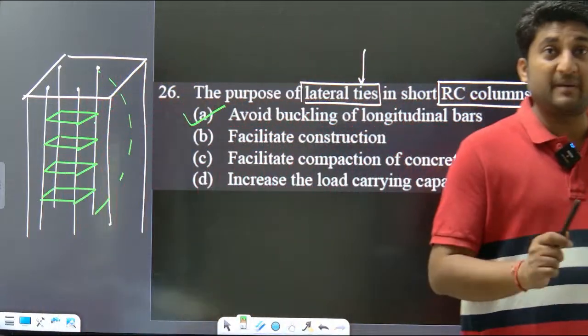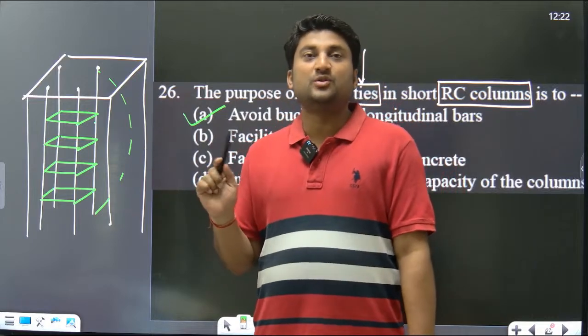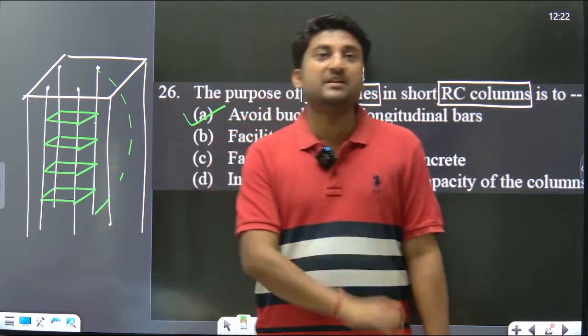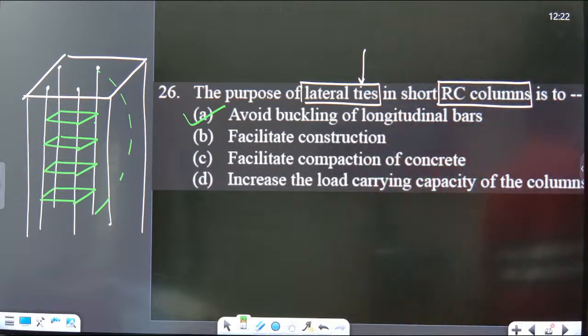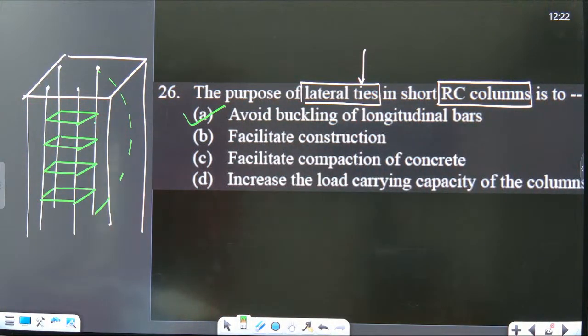No. The main purpose of lateral ties is not to take the load. It is not designed to take the load, but rather it is designed such that buckling of the longitudinal bars is prevented. So this is the main reason. Please put a star mark on this. Arun Kumar, yes, this is the correct answer. Option A is the correct answer. Understood everyone? Clear? Shall I move ahead?